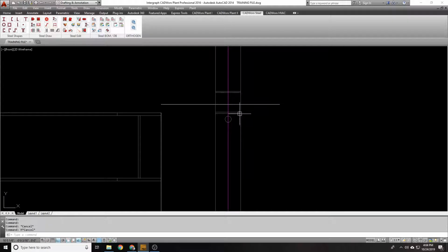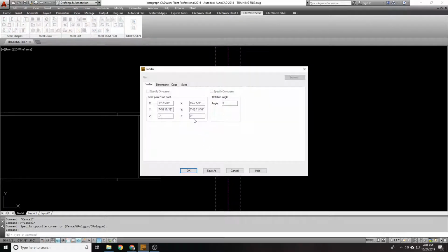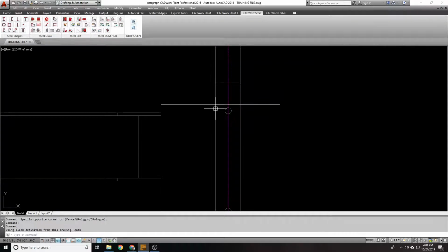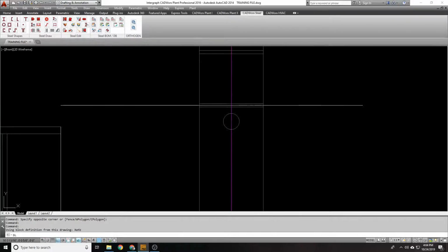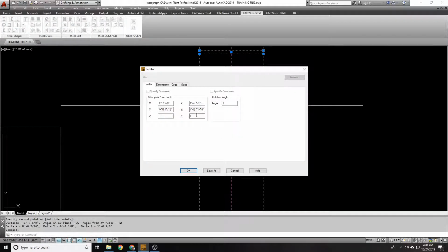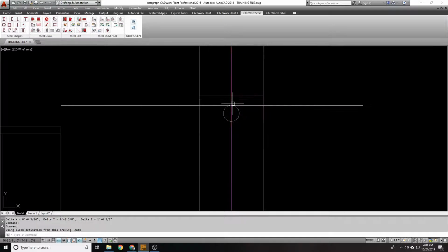So in this case, this will be 1 inch higher. But even still, it's not exactly there, right? We're still 3/8 of an inch from here to here. That y-axis shows 3/8 of an inch. You're going to have to add that 3/8 of an inch onto this, so it's 1 3/8. And now we're matched up with the top of our grading.